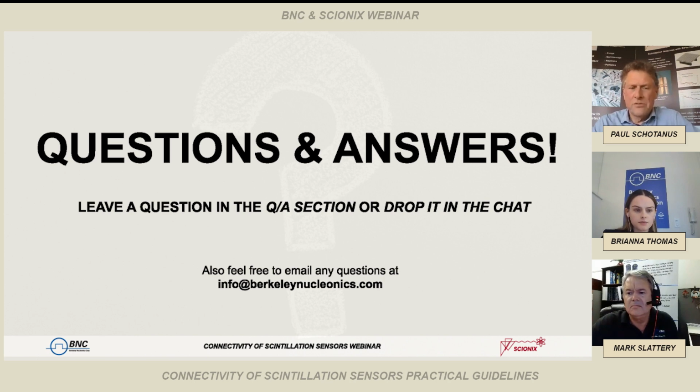I only know that the Cockcroft-Walton bases I'm aware of, the ones that we integrate with scintillation sensors, always have a negative high voltage polarity and therefore feed out DC anode signals. And on digital bases, I'm not 100% sure. So I don't have a good answer to this question. I will look into it.